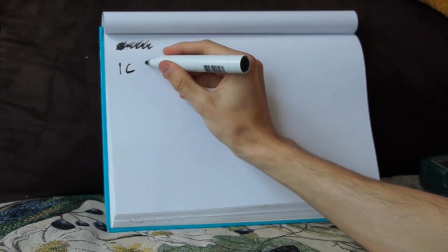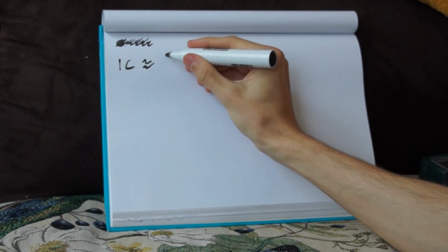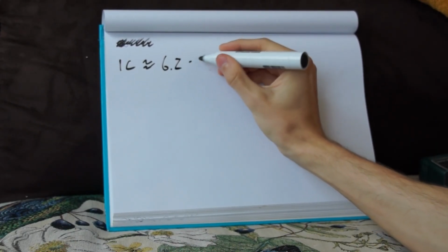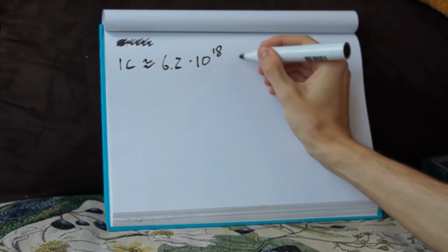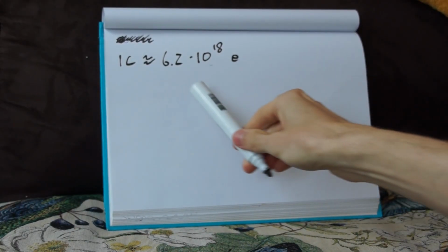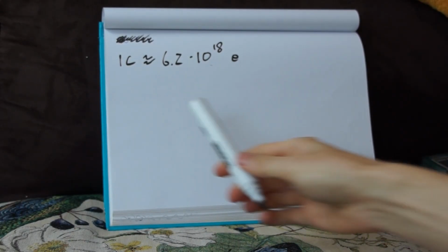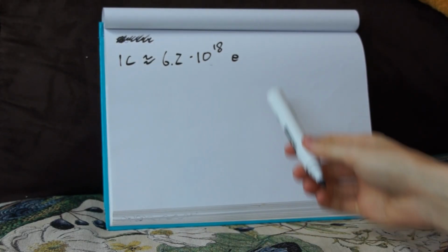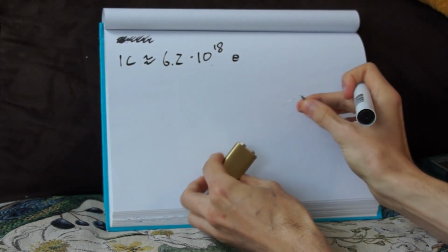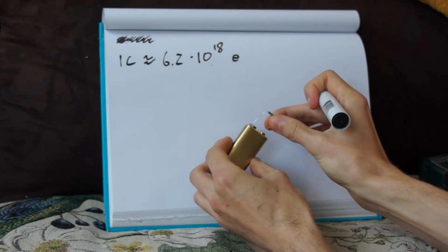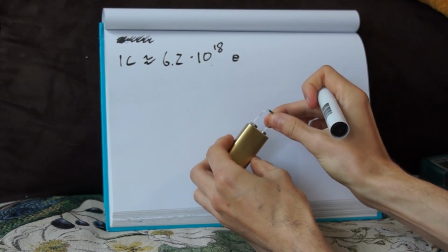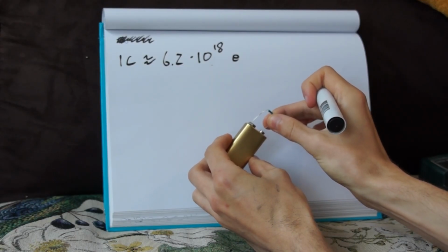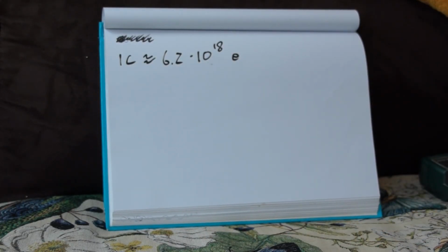Earlier I said that electricity consists of moving charges. So charges are measured in coulombs. 1 coulomb is approximately 6.2 times 10 to the power 18 electrons. Or rather the lack of this many electrons, because a coulomb is a positive charge, whereas an electron has a negative one. When I connect my 900 ohm resistor to my 9-volt battery, we can calculate the amount of electrons that are flowing through the system using what's called Ohm's law.